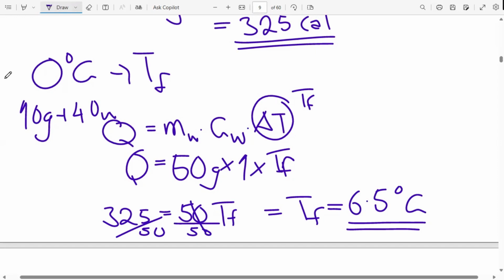I just want you to understand this one so that you are also able to apply it where necessary. So the only thing you're supposed to follow is first find the energy that is required to change the state of your ice from negative 15 degrees Celsius to liquid water at 0 degrees Celsius. Then go to your right-hand side of the equation and find the energy that is going to be released when you change the temperature of your water from 30 degrees Celsius to 0 degrees Celsius. Then find the difference between the two, and that remaining thermal energy is the one that will be responsible for changing the combined temperature of the water now from 0 degrees Celsius to the equilibrium temperature, which we don't know in this case, the T final. And you use this approach to find your equilibrium temperature. So that was question 3A.